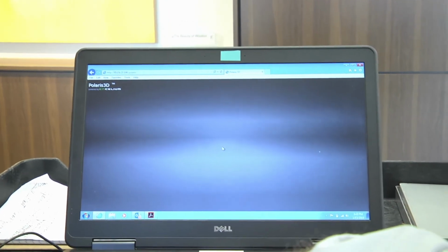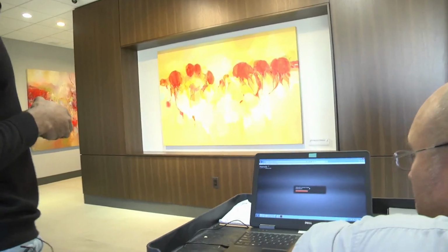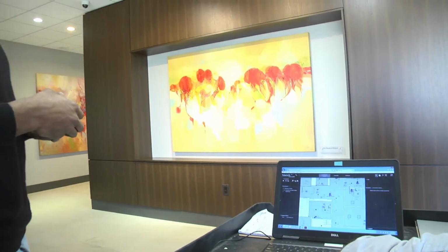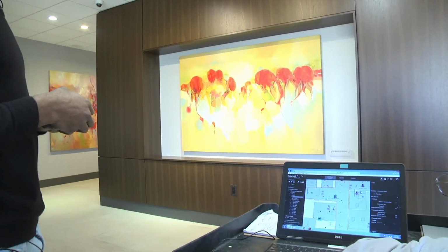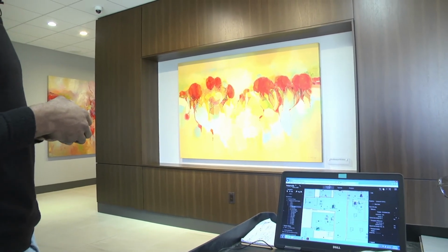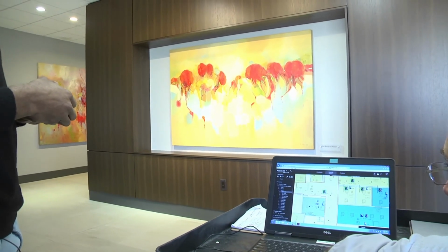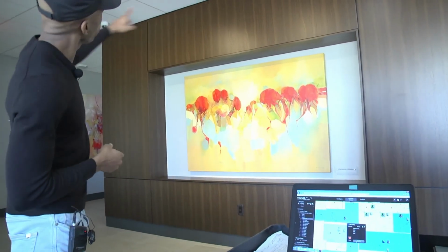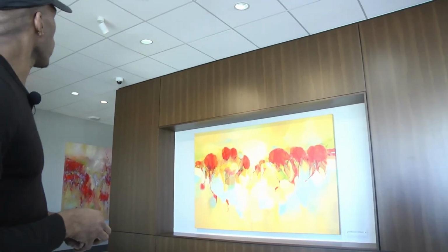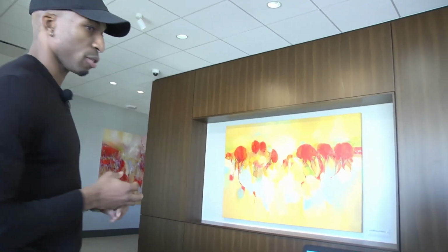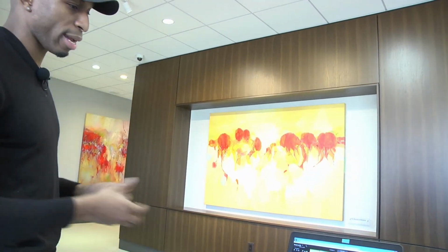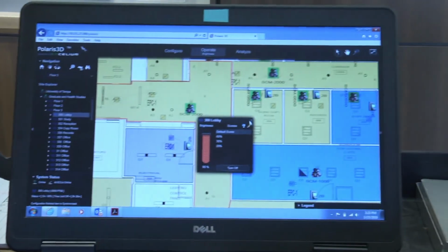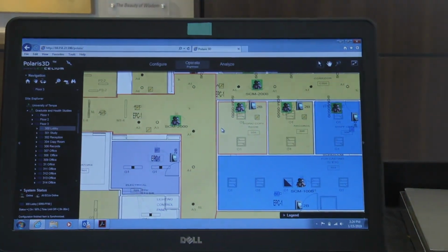Perfect. And then you can test it again by going into the operate brightness mode, and you can turn the zone off, and then you notice that it will not go off completely. It will dim to 20% like everything else in the zone. Proper mode, operate, brightness. Then click the zone, yep, off. Notice it's now dim, it's not off. So you've successfully programmed the section. So you can turn it back on, and then it will react like everywhere else in the zone. So here concludes the programming of this section on the 3rd floor. 3rd floor lobby portrait complete.